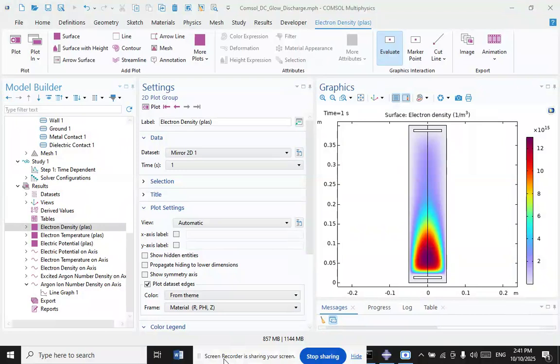And what about collisions and ionization? As these electrons travel, they collide with neutral gas atoms and molecules, transferring energy and causing ionization and excitation. The next one is secondary emission. Some of these energetic electrons knock out other electrons from atoms, a secondary electron emission, creating more charge carriers. The next one is plasma formation. The continuous process of ionization and excitation maintains a steady self-sustained discharge, creating a luminous non-thermal plasma.